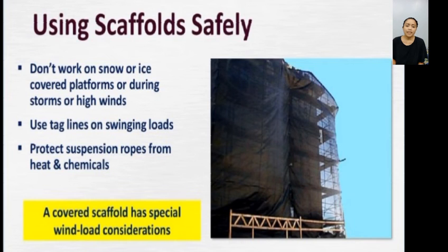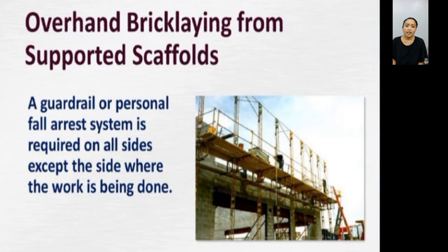Using scaffolds safely. Don't work on snow or ice-covered platform or during storms or high winds. Use taglines on swinging loads. Protect suspension ropes from heat and chemicals. A covered scaffold has special wind load consideration. Overhand bricklaying from supported scaffolds.